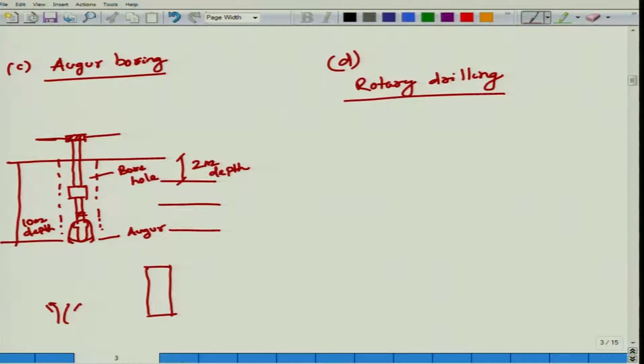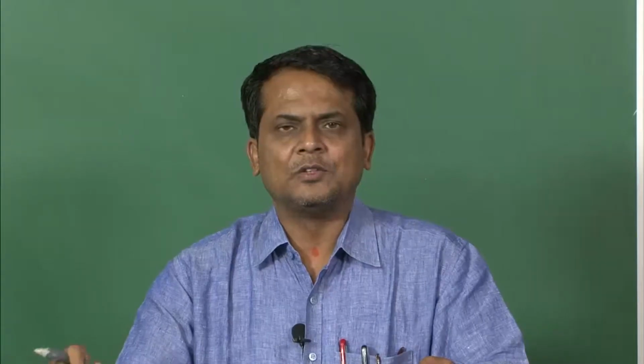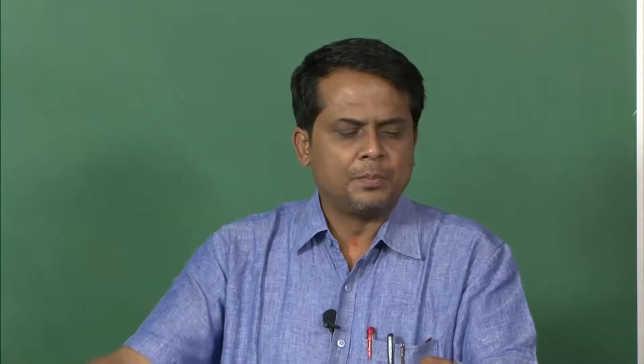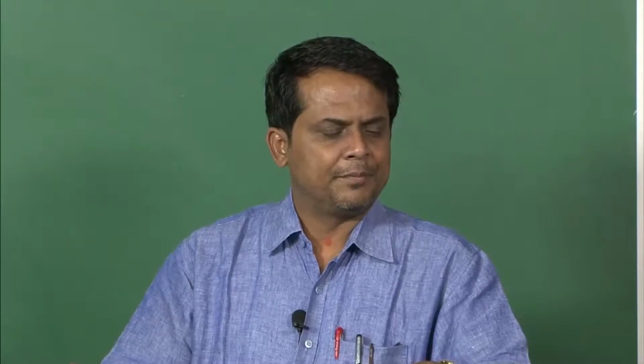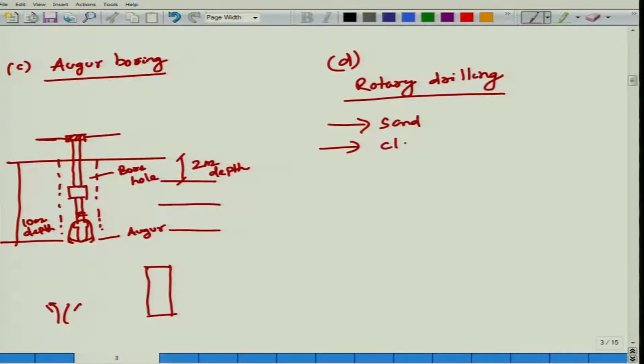It is generally done by means of drill bits and it is advanced. I am going to show you some PowerPoint presentations as well as videos. Whether it is a hard stratum or a soft stratum, by means of drill bits you can make boreholes, and at the same time you can collect undisturbed soil samples at any depth. It can be used for any kind of soil, sand, clay,